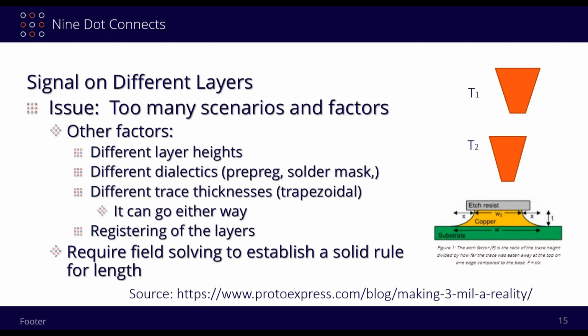Okay? Well, now you've got a registration issue, because are you going to get them exactly on top of each other? In some cases, there's going to be expansion. And some of the new materials may have lower dielectric constants, which you want for high-speed design, but they have a tremendous impact on the way you can manufacture stuff.